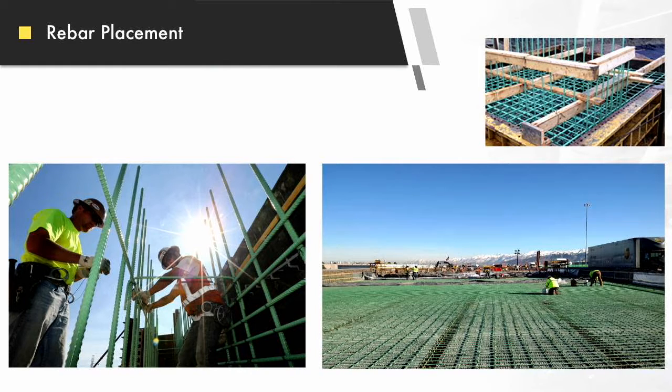These are just some good pictures of proper rebar placement. At least I believe on this one here, they got their strip chair all the way along the form, tied on, so that they've got their proper clearance on that. They're using those are just tops of abutment bars, the U bars on the top to get their clearance there. They have not set the back form. Once they get that all tied up, you can do a really good inspection before they set that form of all your ties and making sure that everything's proper. They set their outside form up with the chairs already attached, and then you know that everything's good.